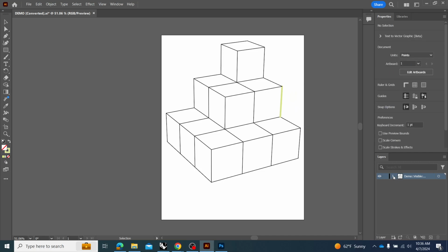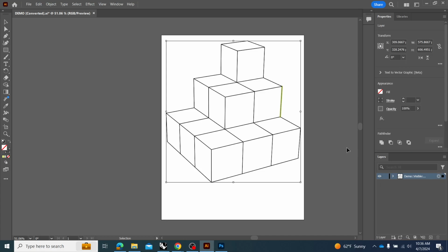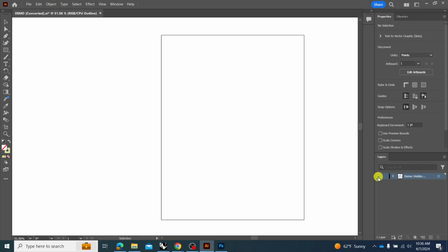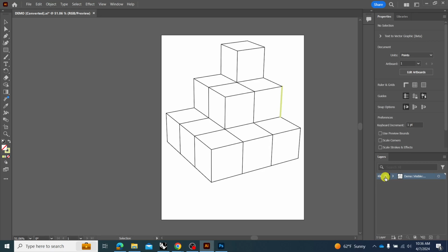There's also something to do with layers, which is more useful whenever you have more layers from Rhino and you maintain those source layers. It will maintain all those sources. Right now, since I only have one layer, it's showing me all the lines in that layer. In order to select everything on a layer, you can select this little circle, and it'll select everything on that layer. Similar to Rhino, you can also hide layers, as well as lock them to not edit them further.